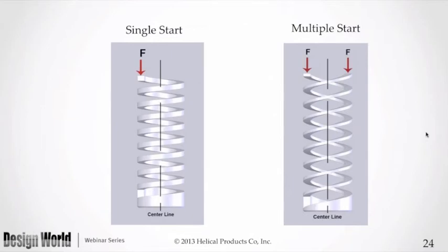You can do it, and it can be just fine. There are times when those moments can be attached. It can be resolved by attachments or in seating devices that are used for both wire and machine springs. But they're there, and they can also be a problem. In a double-started, multiple-started spring on the right, you can see those two forces, but the distances are opposite, and that makes the resulting moment different, and the moments resolve inside the spring to 0.